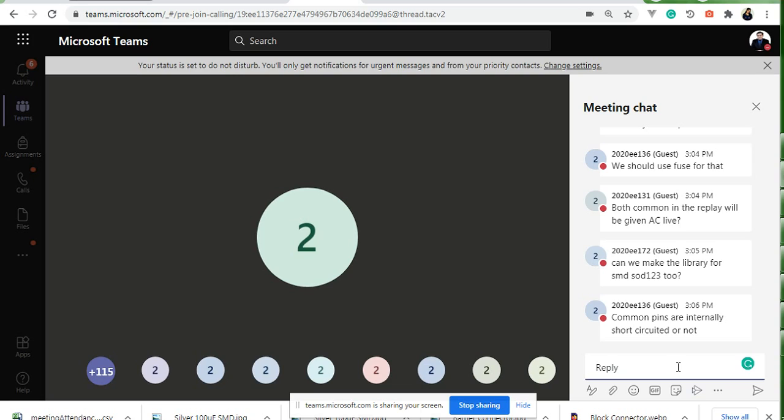So they have to edit your PCB, and then when we order those SMD PCBs and all those vias, I will tell you what the hole size should be. At that point, it will be very difficult to ask the manufacturer to make the via holes of just 0.6 mm and the other holes. I have asked, and there have been some cases where they missed some holes. So I have told these cases to EPCB.pk and Al-Jalil also.